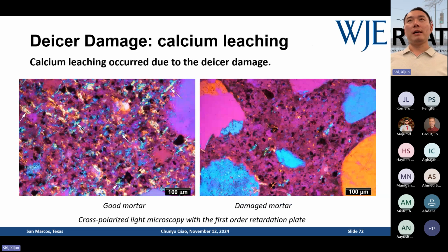Also, calcium hydroxide can react with calcium chloride. So calcium hydroxide can be extracted from the paste matrix and redeposited in the voids or in the cracks. But will that make your concrete more porous? Because 20 to 25% of the paste volume is made of calcium hydroxide. If all those crystals go to react with the de-icers, it's literally like your bone losing calcium: it becomes more porous and more prone to fracture. The same deal applies to concrete. You have a higher matrix porosity, you have a lower mechanical property, right?